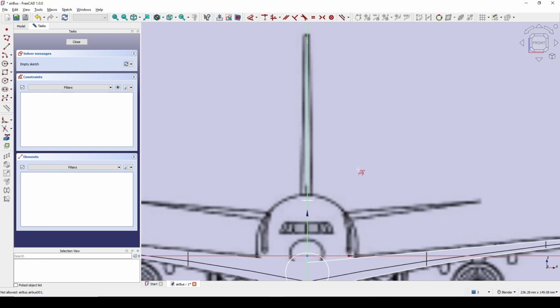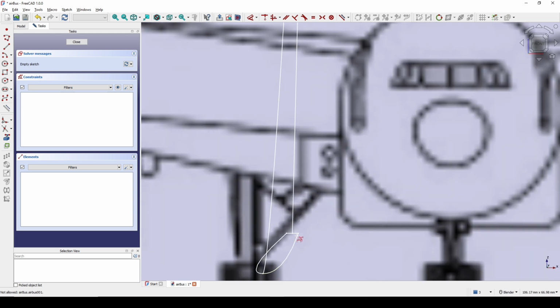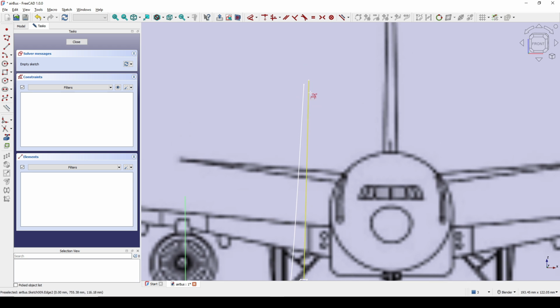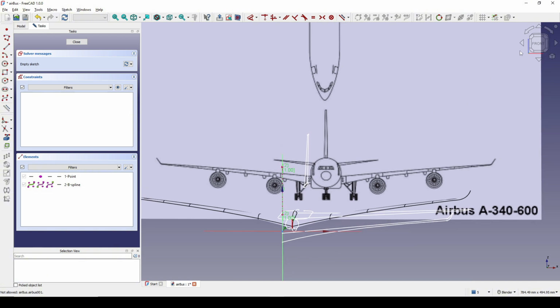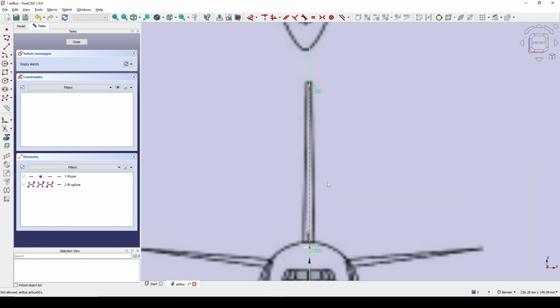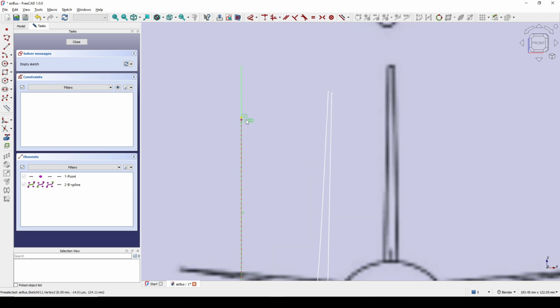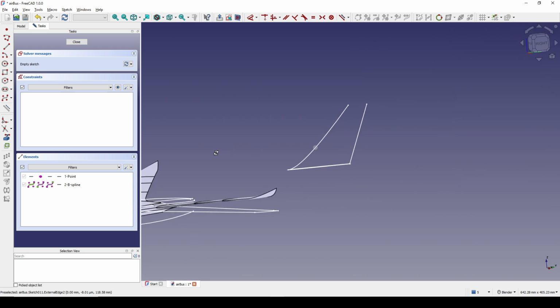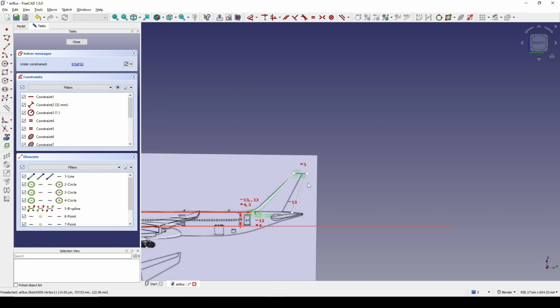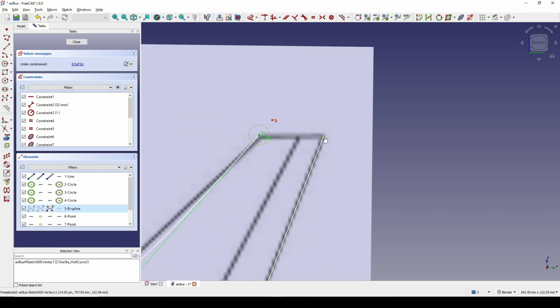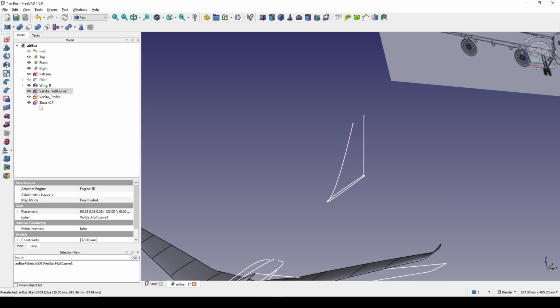And I will reference, let me rotate the sketch a little bit. This part up here. Okay, let's reference this line and go back to the front view. And let's see, maybe I should go back and put these 2 points horizontal. I go back to this sketch, selecting these 2 points, hit H for horizontal, yeah, then I close, and I go back to the new sketch.